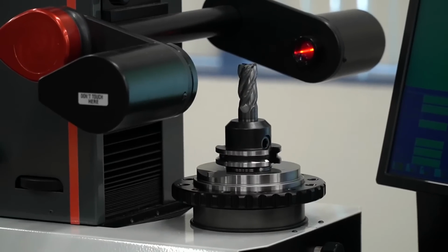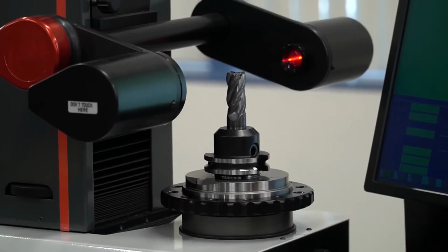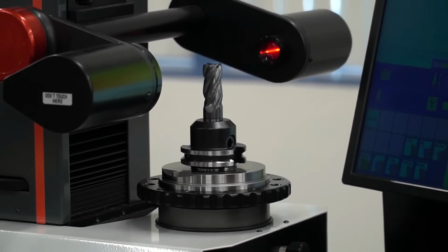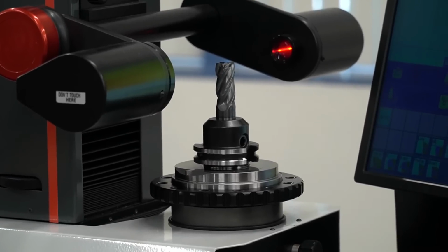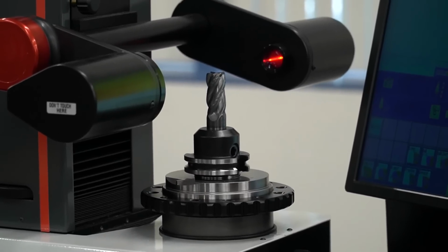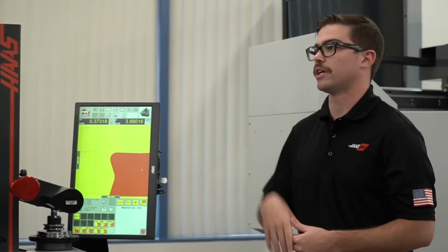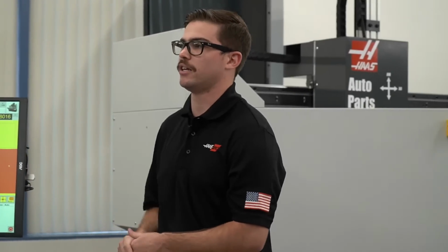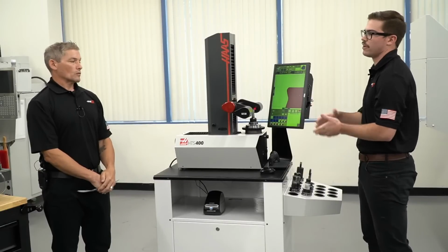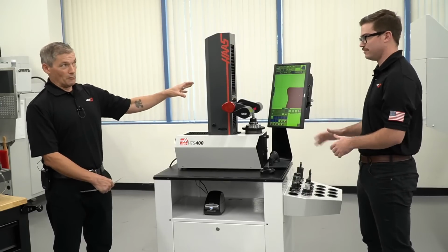So once you've created a folder in there, let's say you checked a tool initially, then once you load a new end mill or you put new inserts in that particular tool, you just come back here and measure it, and it updates that particular one. You select that file and update it as the differences in length and diameter change slightly, right? Correct. Yeah, so you can use this if I'm touching off a brand new tool, or if I want to do part inspection, I can pull the tool from my machine after a job, put it back on there, and measure the new tool geometry after I've already machined with it.